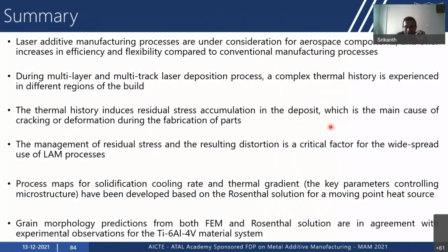But in the LAM process, either single track, multi-layer or multi-track, multi-layer, the layers experience a complex thermal history in different regions of the build. The thermal history induces residual stress, and this is the main cause for cracking or distortion of the parts. The management of residual stress and resulting distortion is very important for the widespread application of the LAM process.